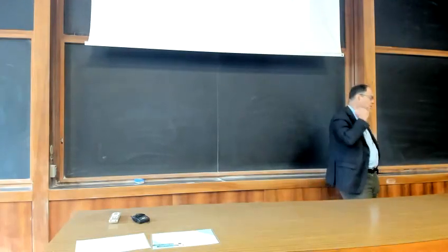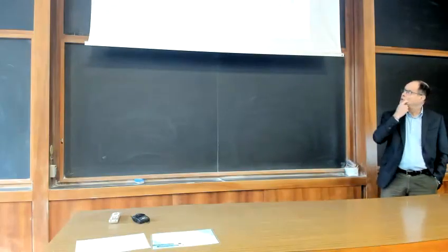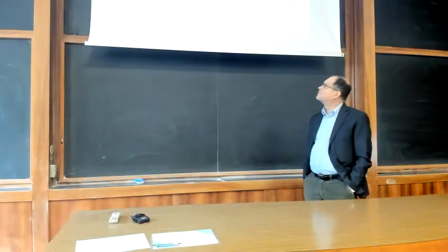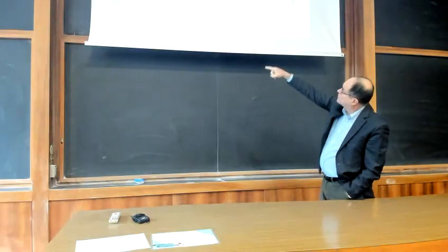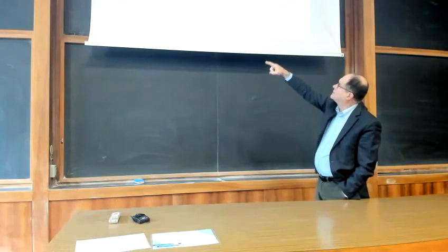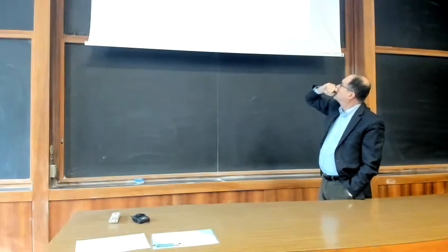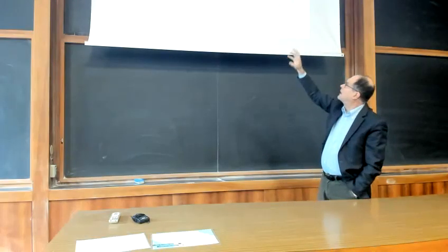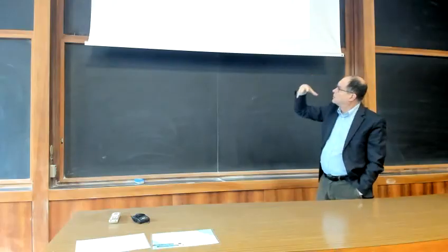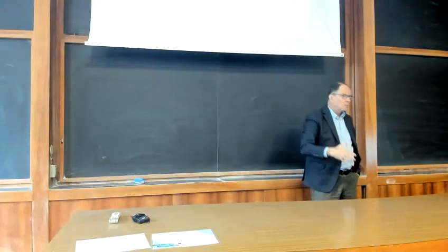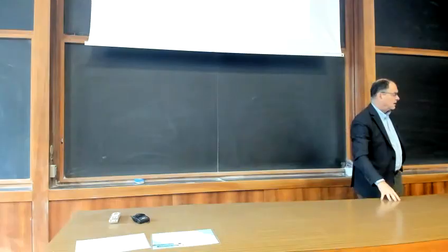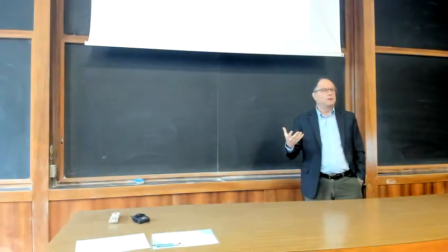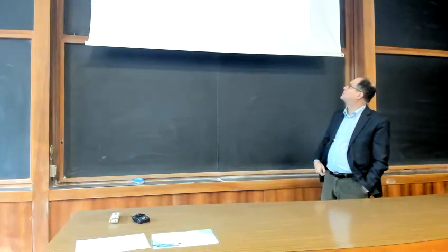When you unload, you recover only very little settlement, as you can see from those unloading and reloading lines along the curve. Essentially you never reach a final value, but the more you penetrate into the soil with your foundation, the higher is the load supported by your foundation.